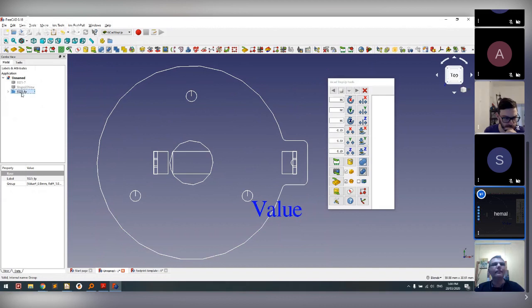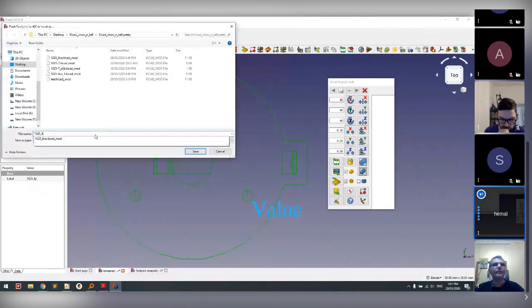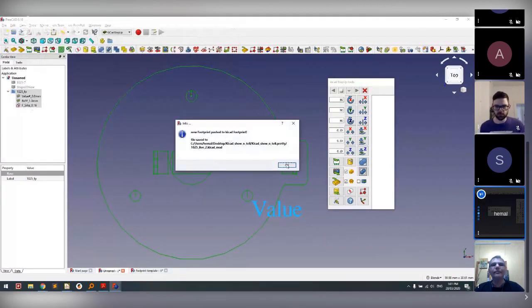Once you have this group with all three listed, you click on this icon, which has a footprint and a red arrow on it. It says footprint editor and exporter. As soon as you click on it, it will ask you for a name. I'm going to do another one and save that. So it exported the file. Basically, it wrote the file.